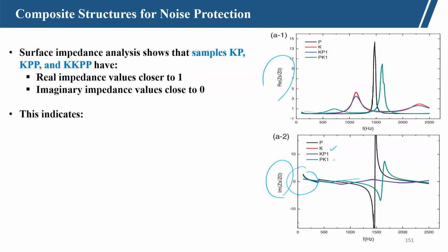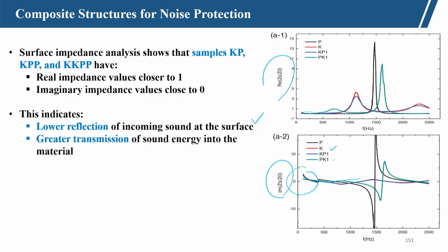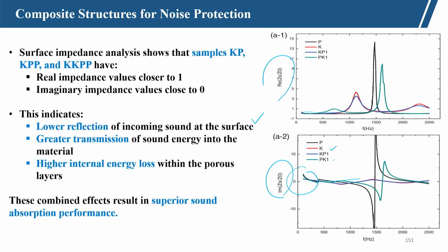This surface impedance analysis indicates lower reflection of incoming sound at the surface, greater transmission of sound energy into the material, higher internal energy loss within the porous layers, and this combined effect results in superior sound absorption performance.